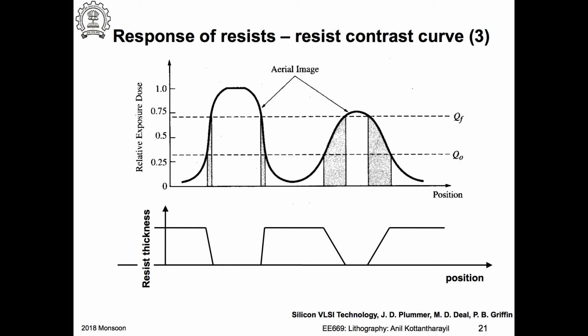most of the time the lift off process is seen to be a very difficult thing to reproduce for most of our students, and one reason that I have found is that nobody does any analysis of the profile of the resist after you actually develop it. Okay, so when you do this lithography, one of the very important things you need to worry about is actually the profile of the resist.